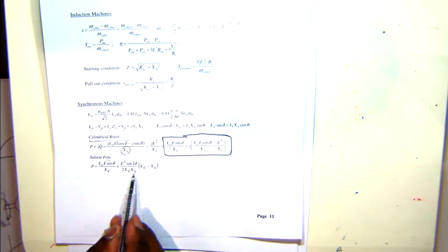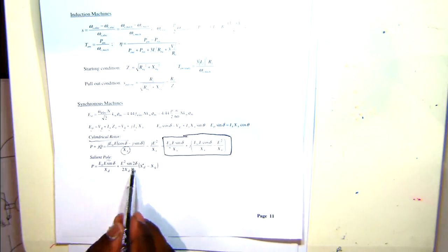But then there are other types of synchronous machines called salient pole synchronous generators. For that, the Xs changes with rotor position. So that characteristic is factored into two reactances. So that's this equation. In this course, we won't go into salient pole synchronous generators.